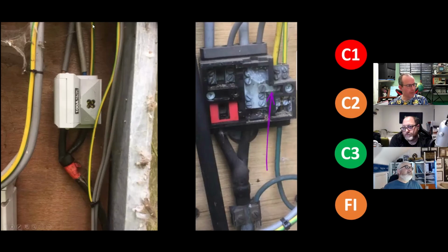Oh my God! Well, that's definitely not a DNO one because it's not in any of their manuals anywhere. That's definitely not a DNO cutout. I can't see that being an approved method of connection. But it was one that got sent into us, and I just thought it was mind blowing because I've never seen one in 20 odd years of looking at this and studying this, and this is in none of the manuals whatsoever. Trust me, I've got them all sitting on the floor. I've seen cutouts with a bung on them, but I've never removed it to see underneath them, so I guess that's what that is.